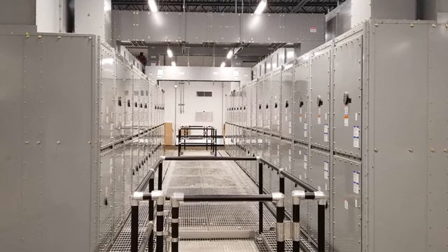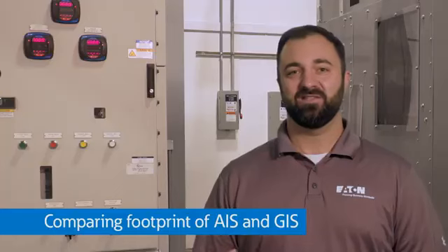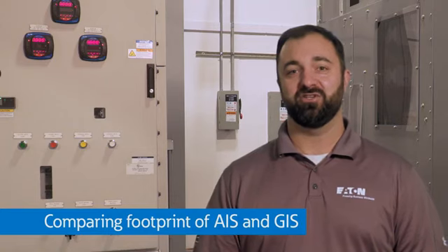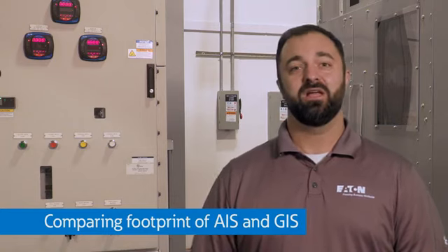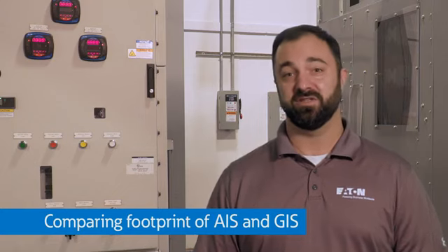In medium voltage applications, selecting between AIS and GIS can be driven objectively by understanding the differences between the equipment. Today, the bulk of installed equipment is air-insulated switchgear, yet gas-insulated switchgear can provide advantages in certain applications. As we'll discuss, one main advantage of GIS is potential footprint savings. In order to determine the right equipment to apply, it is best to understand how the equipment is being designed,